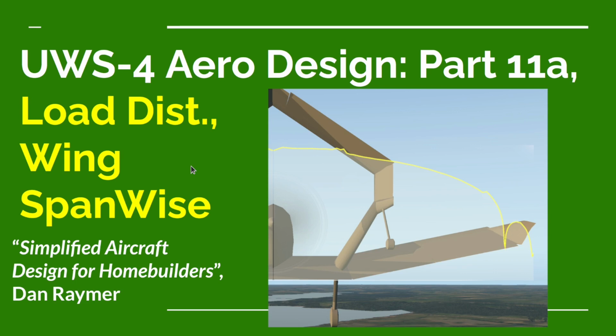The reason it's going to be pretty difficult is we're using fairly standard aluminum airplane construction techniques. We're not using lots of high drag tubes and wires like you would see on a traditional ultralight. Because of that, all the strength of the airplane is going to be internal to the structure instead of external, like with wires and a lot of bulky big tubes. That actually makes the design a little more difficult. It's going to add more weight to the airplane, and that's going to drive the simplification that we're going to do in this video.